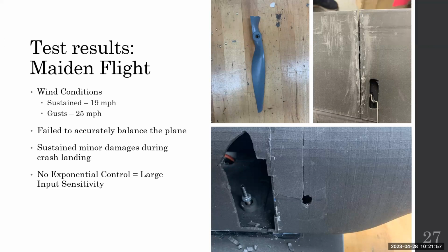Okay, yeah, that's all great. I would like to see that in your presentation. The pre-flight tests are pretty standard for this: taxi testing, CG testing, control surface testing, and then also structure testing if you have time for it.